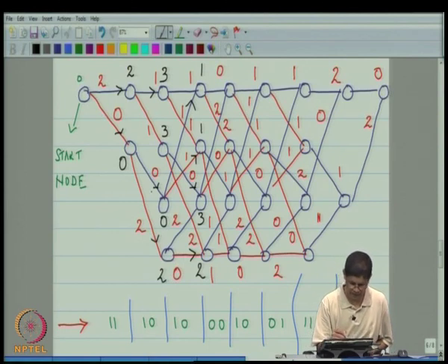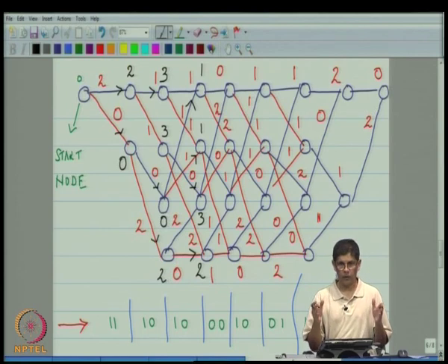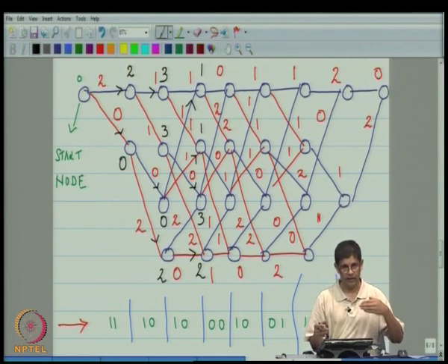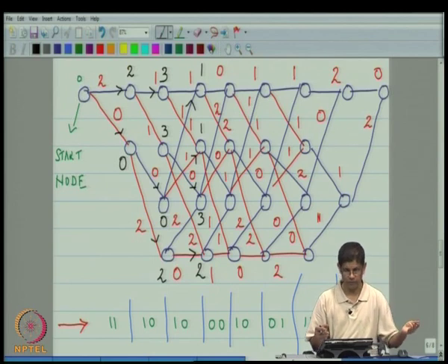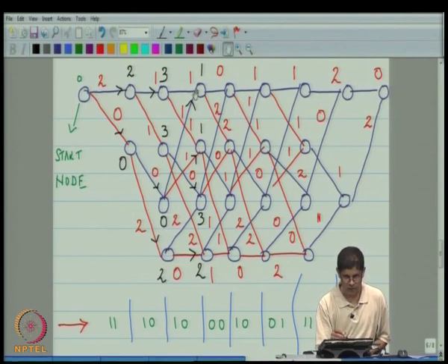Okay. So, in a way decoding is about picking the winner, and the winner is the code word that is closest in Hamming distance to the received vector. What the Viterbi algorithm allows you to do is identify losers, that is code words which can never be closest, and throw them away. So, the first time we actually did that was at this node, because here we had a choice between this and this, and since in this case this won out, this means that this lost. What does that mean?